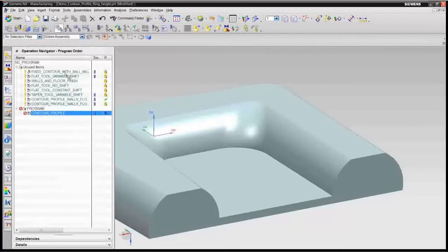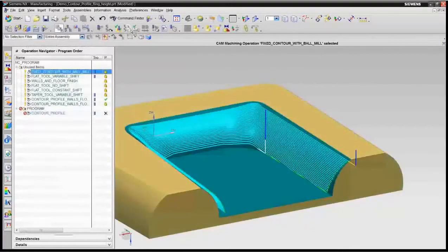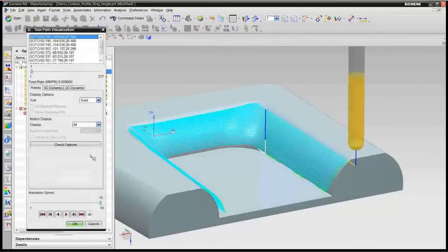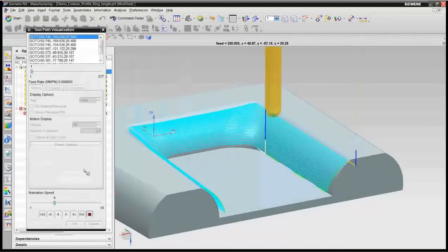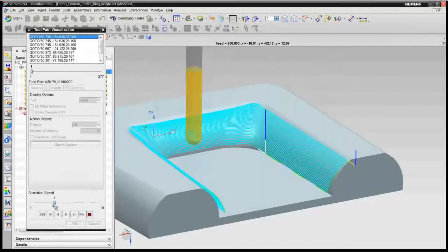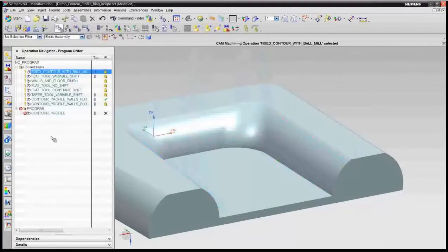And if you come in with just a ball, let me replay this and just show you. The typical tool path that you'd do in the past was you'd machine this something like this with just a ball end mill. The time to do that is actually quite a bit longer. And so what we're going to do is use a contour profile operation.